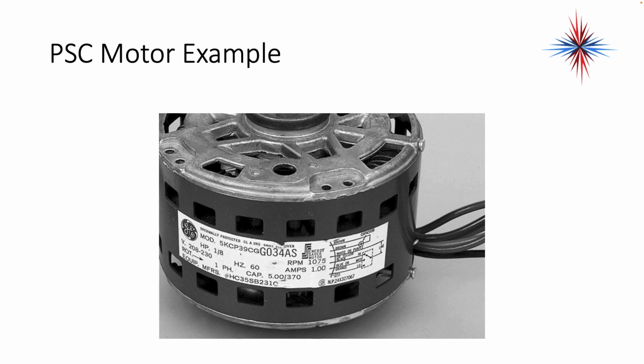Okay, and you'll see in the wiring diagram, if you look close, there's a capacitor there. This is multi-speed, so you might have high, medium, and low based on the color of the wires coming out. Any additional wires, cap off and isolate. Make sure they can't short against each other. Do not put them under the same cap.